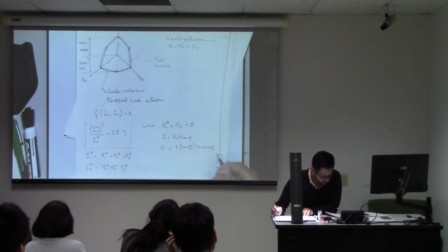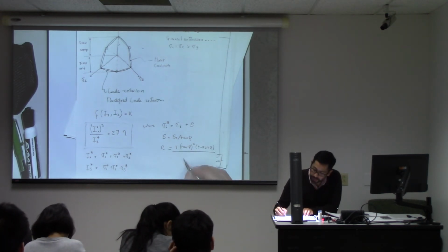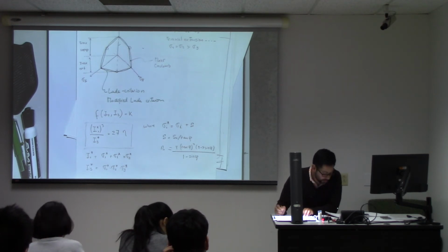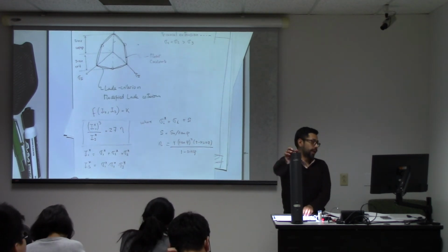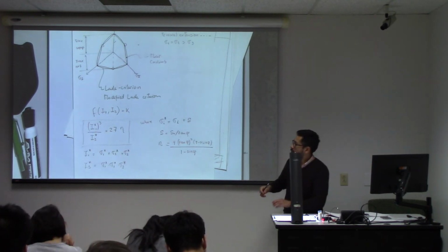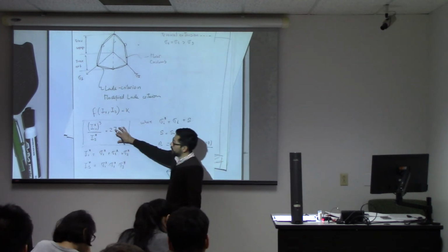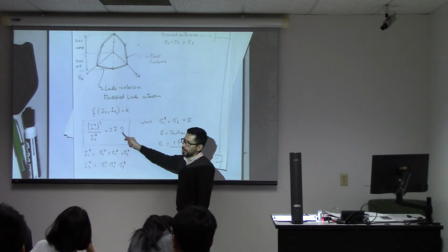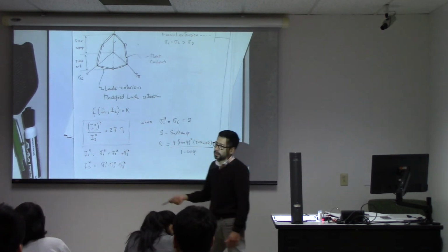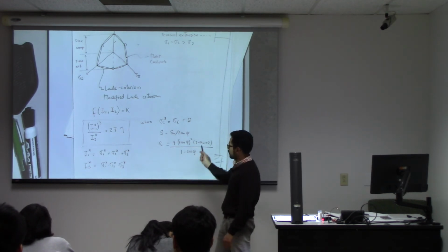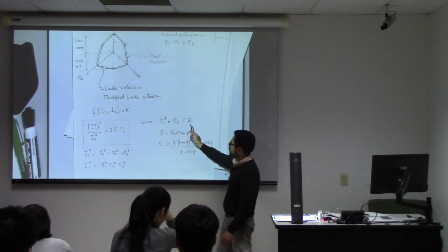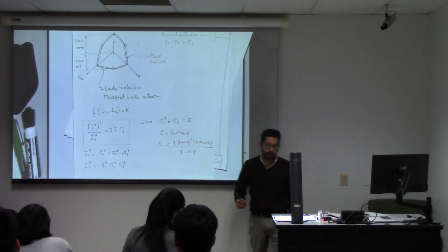So you could go two ways on fitting this Lade criterion. You can run your tests and just make your data fit this equation and find out what the value of eta is. Or you could also run just a regular test, determine the friction angle, and then just plug it into here and just determine that other parameter.